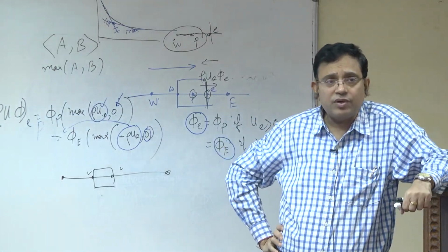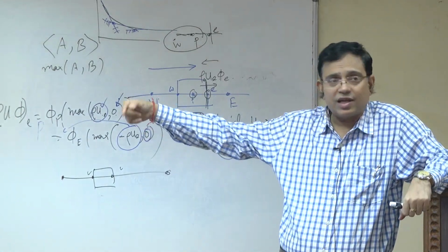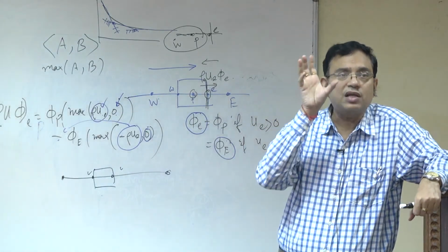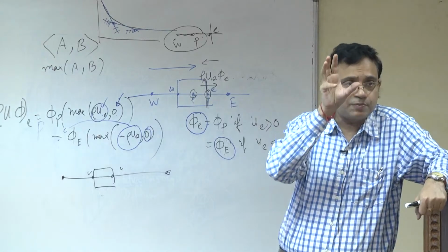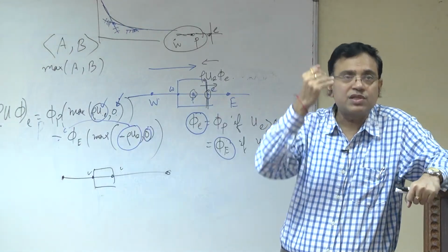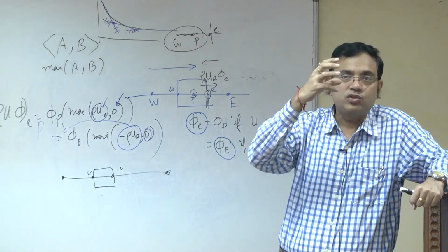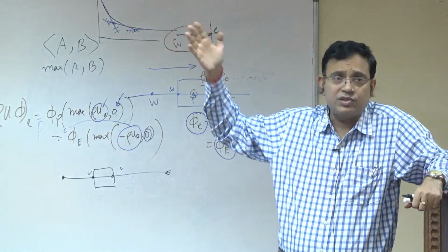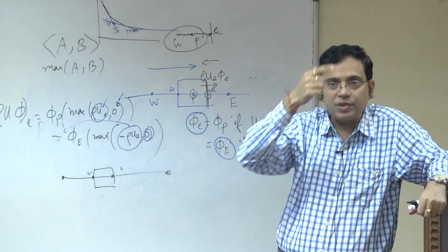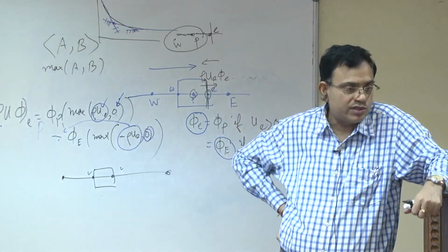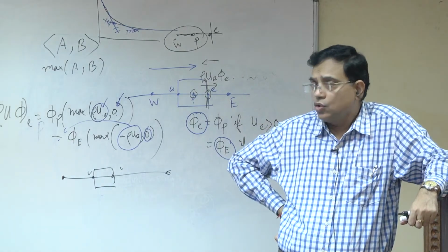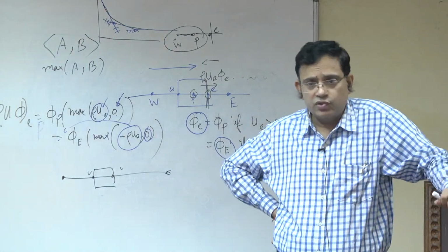But in reality when it is in between, it is exponentially represented in a nice way, but exponential calculation is computationally expensive. So there may be more simplified forms of doing it through other forms of interpolation. One is piecewise linear, which is the hybrid, and representing it by a power law is the power law scheme. Okay. So, this is all about the convection diffusion problem.